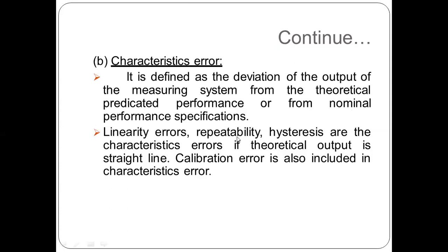Linearity errors, repeatability, hysteresis are the characteristics errors. If the theoretical output is a straight line, calibration error is also included in characteristics.